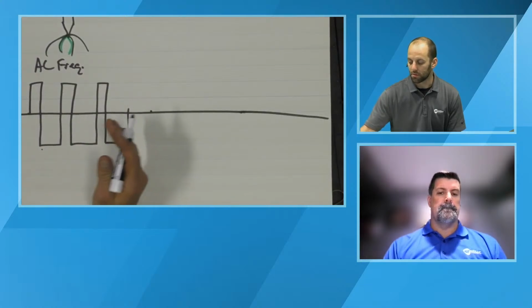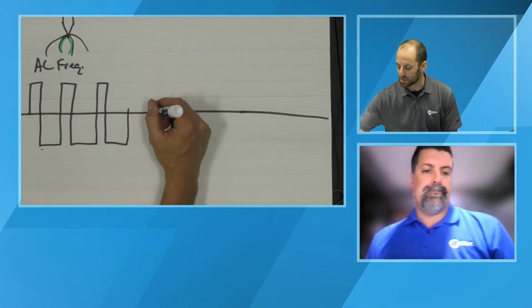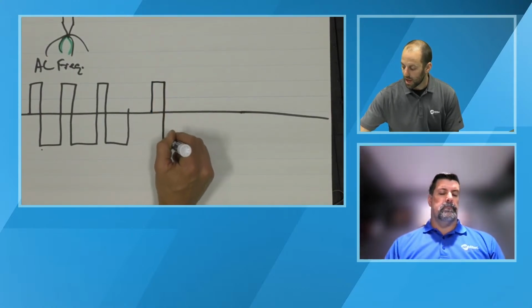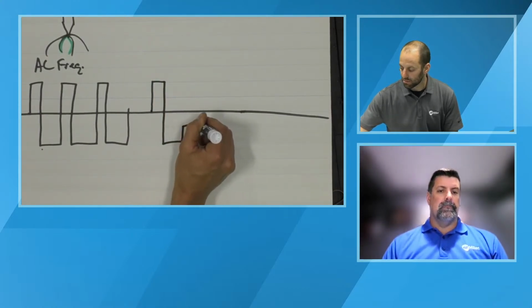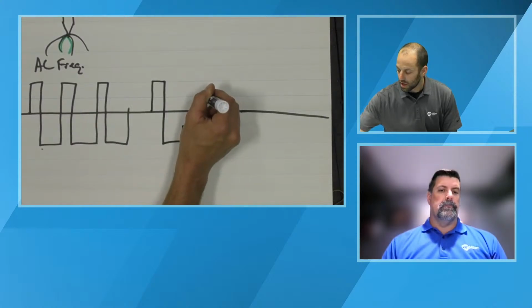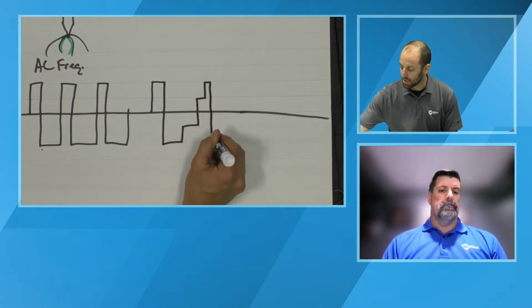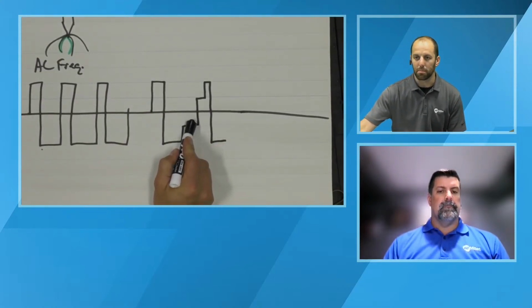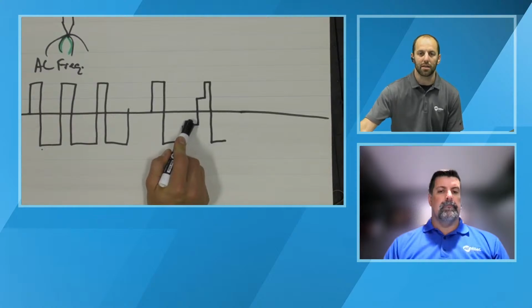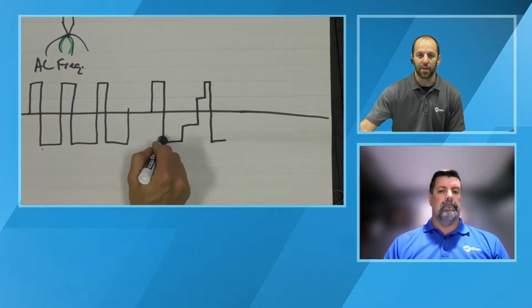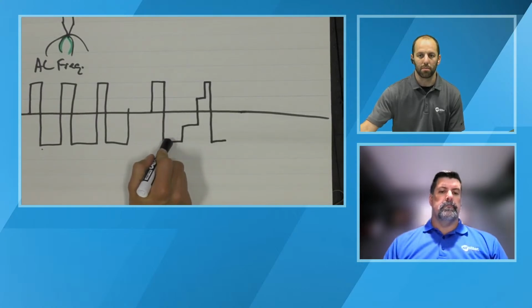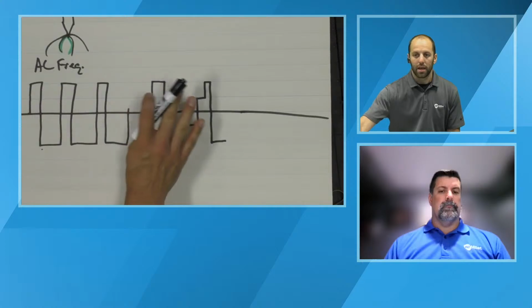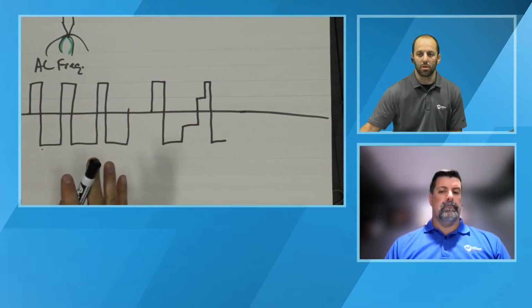Or even if your pulse frequency and your AC frequency are offset, you might end up with a waveform where you go into the background of the pulse, then step up for a short period of time, and you get these really funky looking waveforms as you go between the background amperage setting and the pulse, and then through your AC waveform on the AC side of the machine. So typically, we don't recommend it.